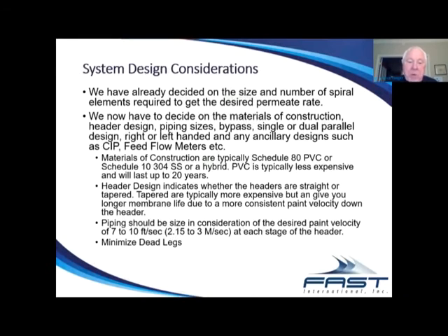We like to use a tapered header design rather than a straight design where the header pipe is the same diameter from one end to the other. We like to change the diameter of the header pipe so that the velocity inside that pipe is more consistent as you pull paint out of the pipe from the earlier elements. And again, we always design that by calculating the velocity for each stage in the header. And then, of course, minimize dead legs. Next.